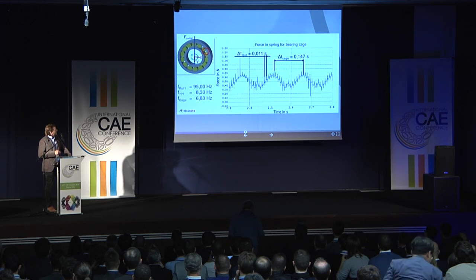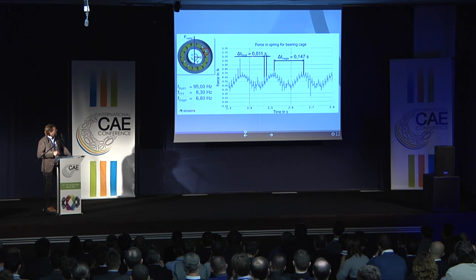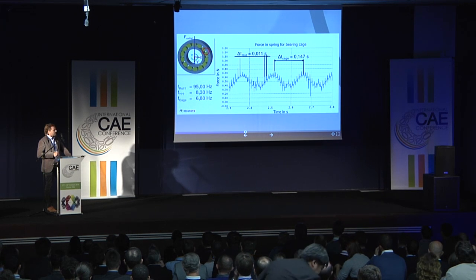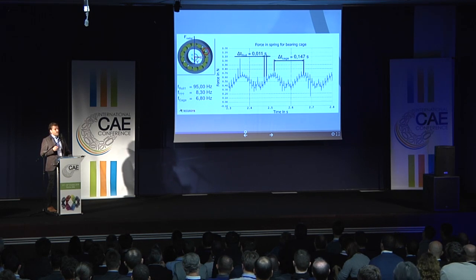Another good thing you can see in this force is these little peaks right here. If you measure the time difference between these 2 little peaks, you come to 0.011 seconds, which correlates with the 95 Hertz, which is the rolling element frequency. So this plot shows us that the dynamic behavior of this bearing model works pretty well. But the funny frequency is still there.